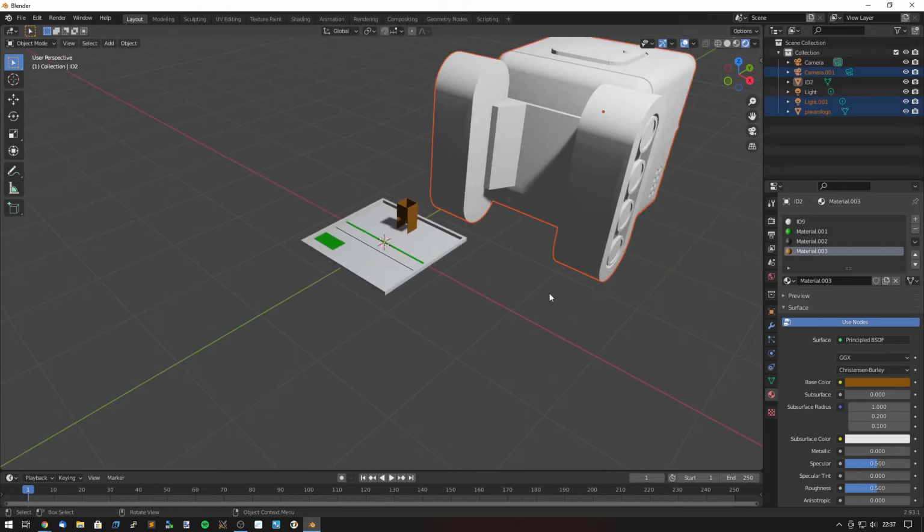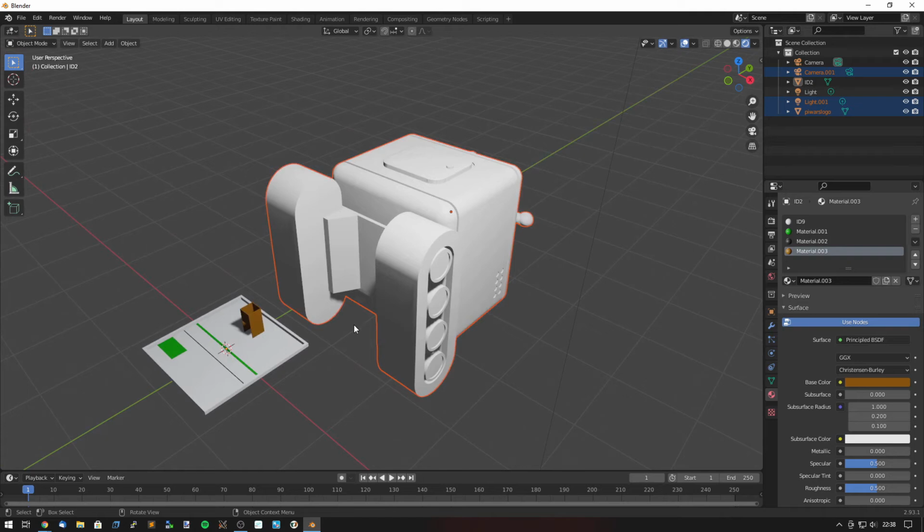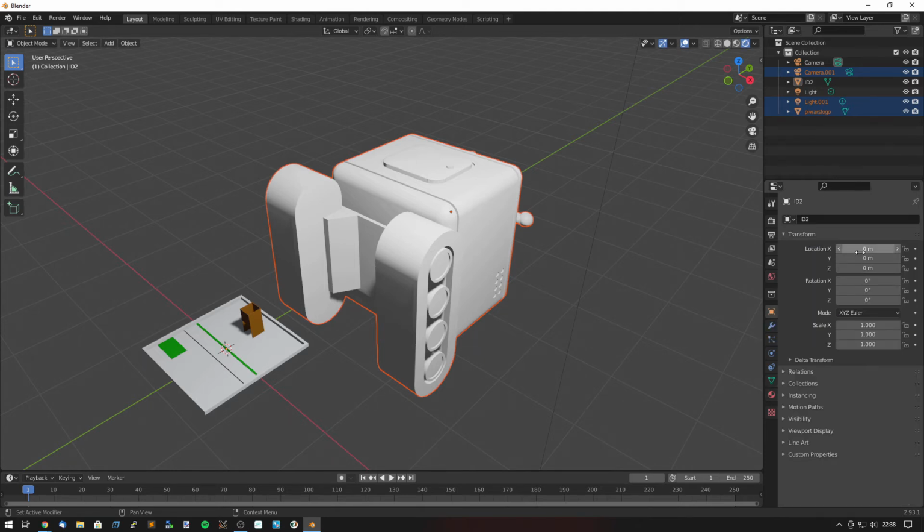And it is huge, and it's rotated onto its back. So depending on how the system was designed or how the file was designed, you may find it comes through in the wrong scale, the wrong orientation, that kind of thing. So the first thing I want to do is probably rotate it so that it's actually pointing up. We can do that one here with the object properties. I can select that tab, and we have the location and the rotation and the scaling.